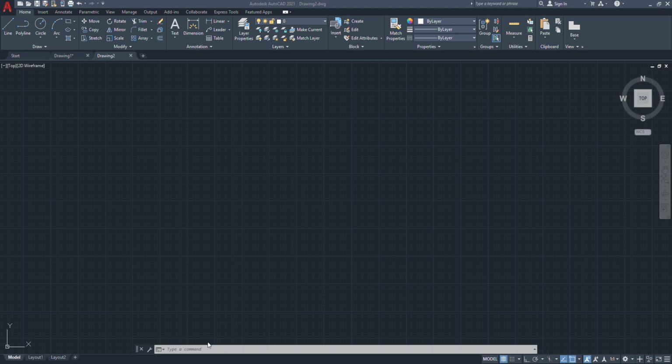First we will set the limits. In the command bar you just type LIMITS, enter. Then it will show lower left limit. Just enter there. Then for the upper right corner you give some value, say 300, 200, based on the dimensions. Then enter again, and once more enter, so that the upper right corner value which we gave is inside that bracket.